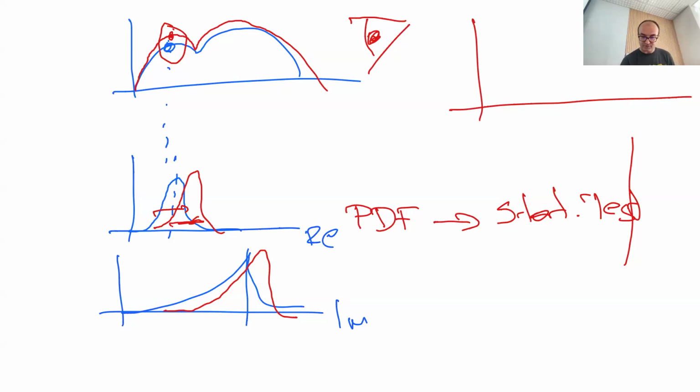Let's say the blue one is the reference and the red one is the current value. We can say there are no changes in this frequency region. There are changes here, no changes here, small changes here. And we can do graphs like this. And based on where these changes occur in frequency, we can do some fault analysis. And this will pop up automatically.